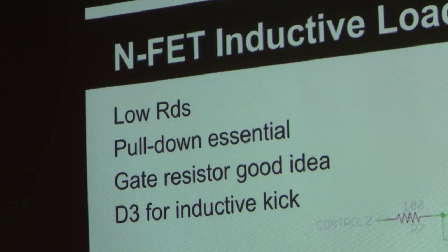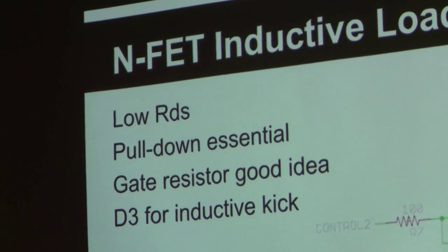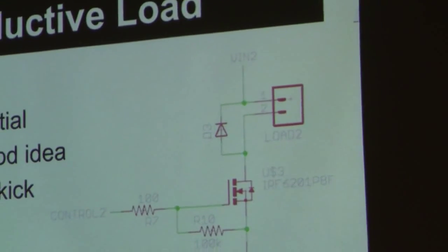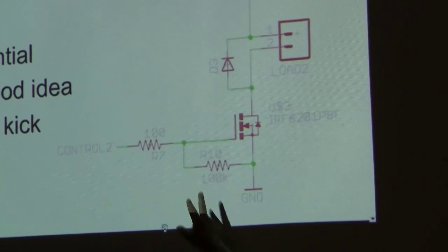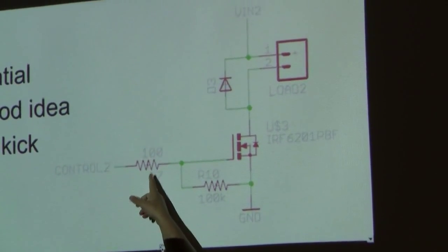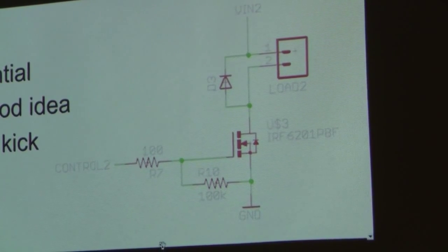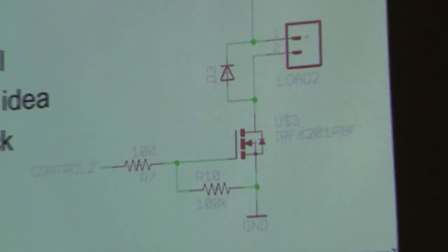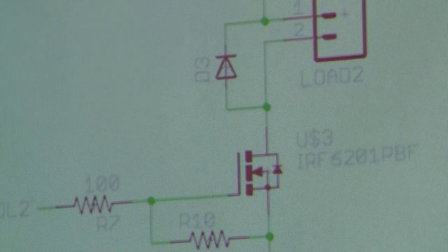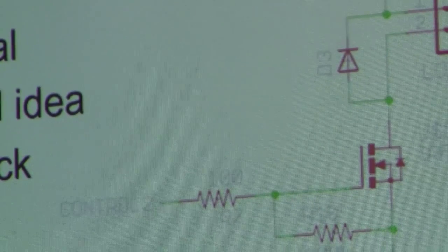The same sort of thing, but notice here where the BJT only needed one resistor, minimum. You had to have that gate resistor. Here you have to have two. This is driving the gate of the MOSFET, and the 100 ohm resistor does two things. One, if you're driving that capacitor with no limiting resistor, you're going to be fatiguing your output transistors.